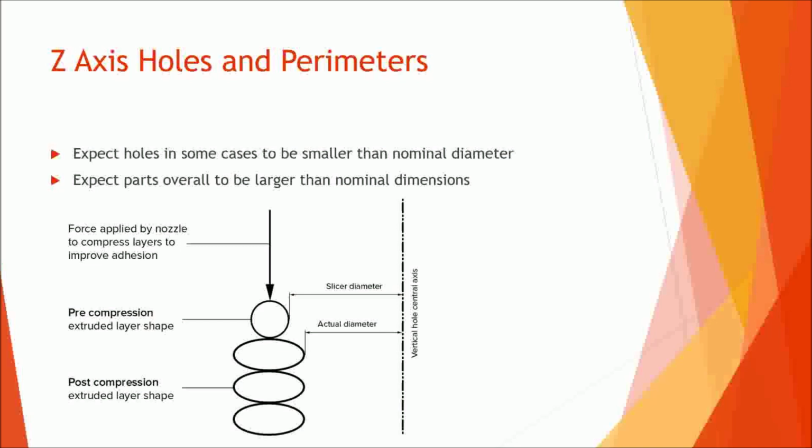the nozzle of the printer is extruding basically a cylindrical piece of material out of a round nozzle. But the nozzle is going to compress each layer a little bit. So instead of a round layer of material, you're left with something with a cross section that's more elliptical. So in the software, whatever pre-processing or slicer you're using, it thinks of it as this round cross section.